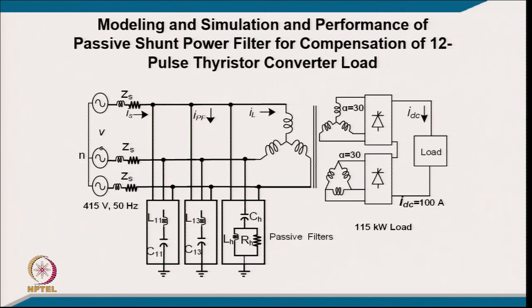I mean equal current certainly will help the balancing of both converter currents automatically, and the voltage rating is increased because both voltages are connected in series. And the isolation is of course providing the right voltage, because in HVDC you go to high voltage. So, this we have from the generation side to go to a high voltage transmission system, that is for HVDC, but for other applications also.